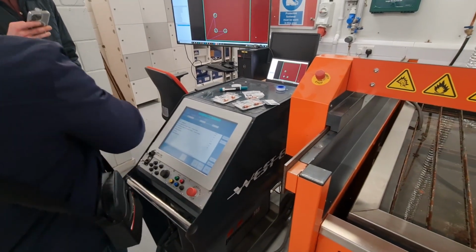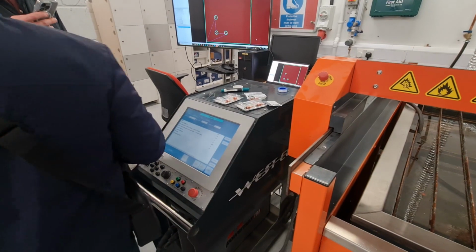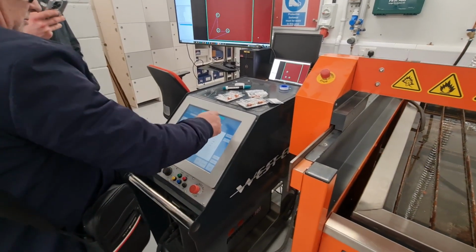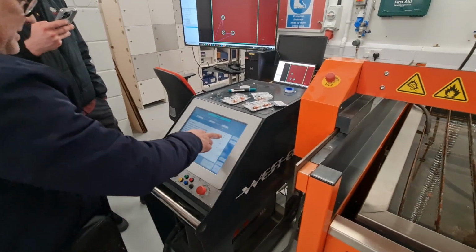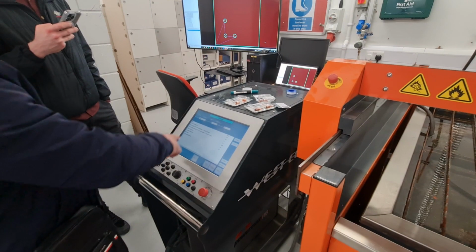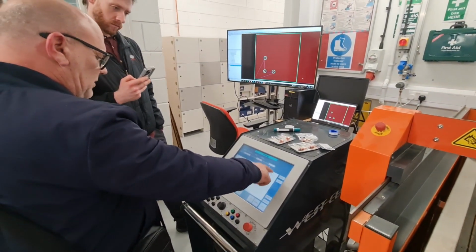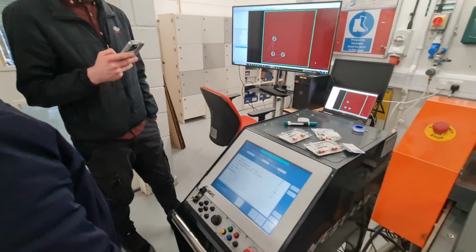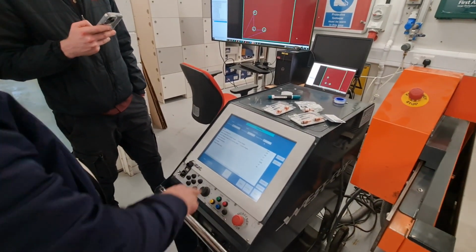So in my experience, I would not cut 65 amp in a 2 mil. I would go 45 amp. So these are the cutting parameters that the machine needs. The arc voltage should be 130, piercing height 150%, and so on. These are all automatically set. You just press apply.